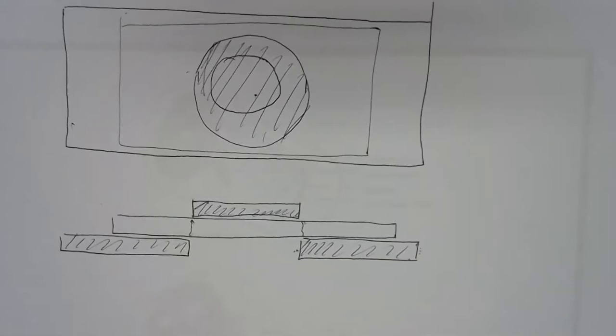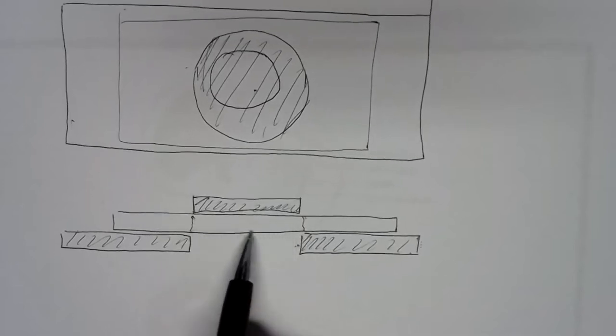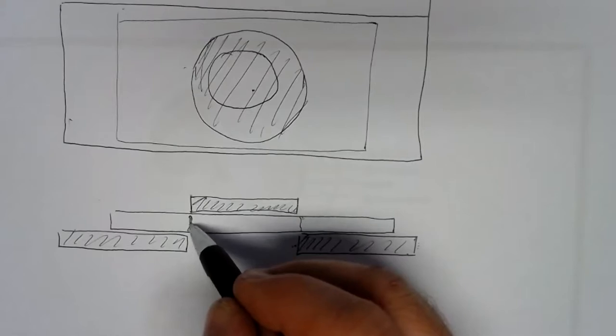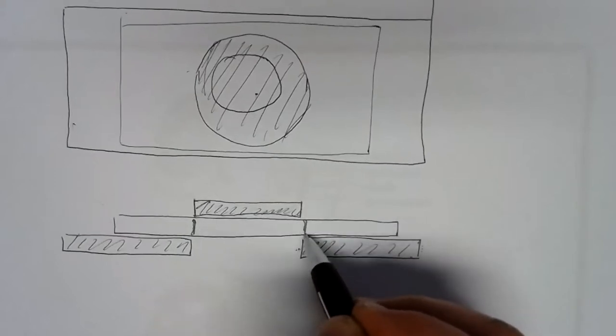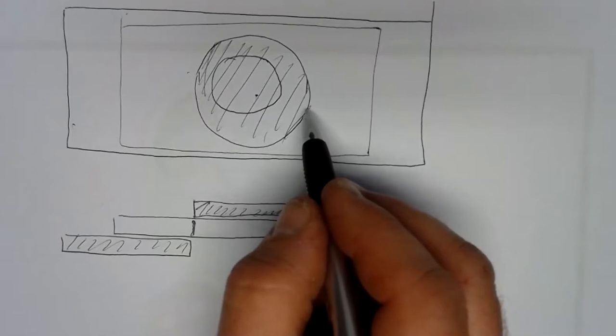Here we have to be very careful about calculating the area that's resisting shear. And you can use that trick that I mentioned a little bit earlier. The best trick I know to figuring out the area is to imagine it broken. Imagine what it looks like after. What's the new material that's been exposed? What did it break through? Well, the area that it broke through is this cylindrical area. It's the cylinder that's the thickness of our sheet metal high and the diameter of our die wide.